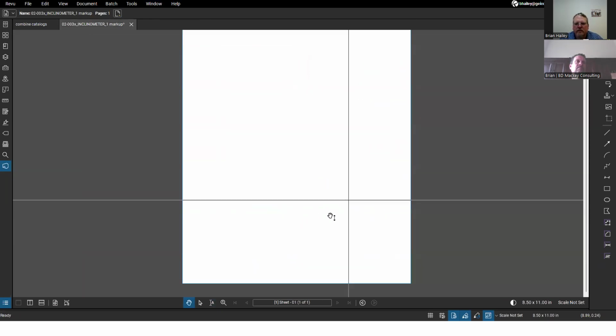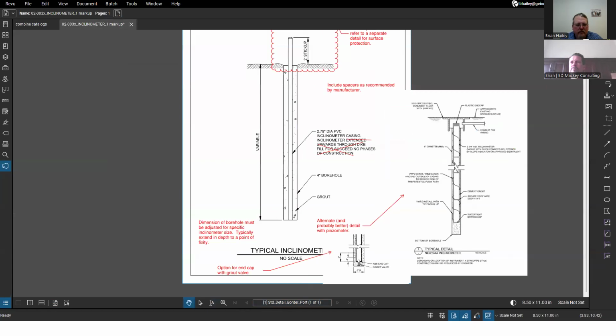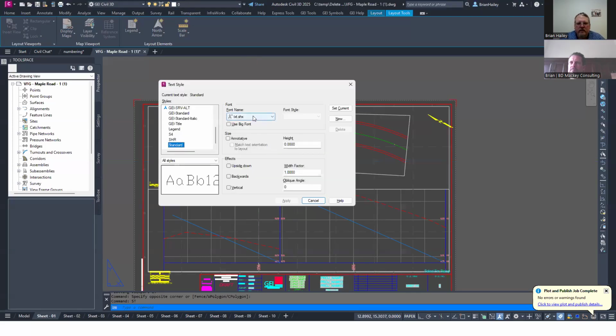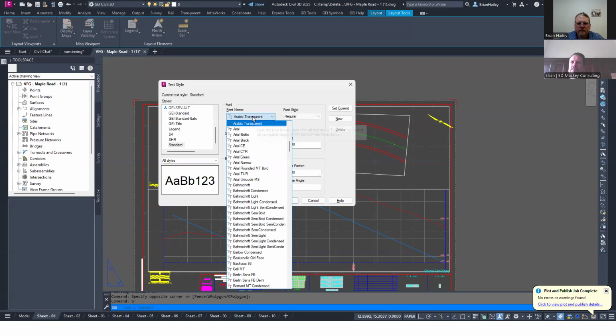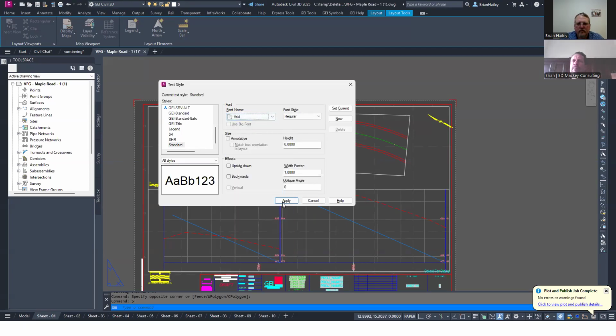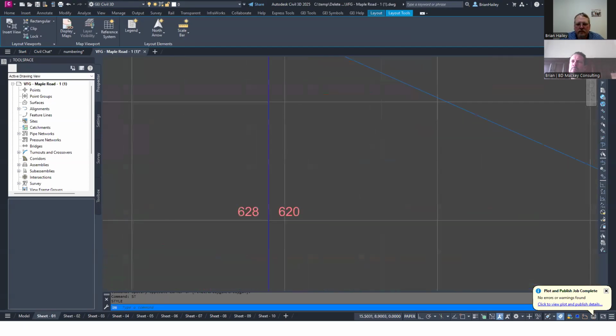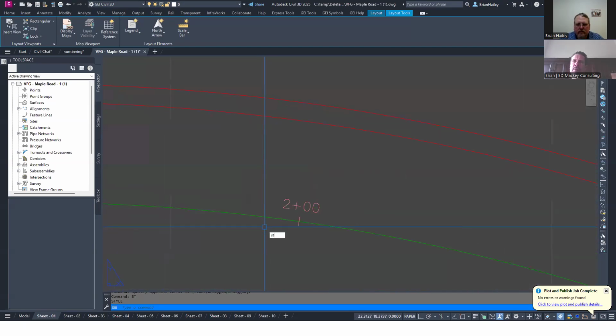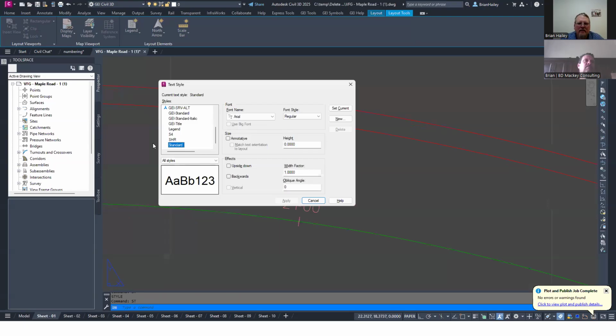All right, let me replot this here again real quick. I hate SHX fonts. And Kyle said he remembered something similar, but it was oftentimes when people used a masking region to hide viewports, and the print function in the PDF didn't always respect the mask, right?